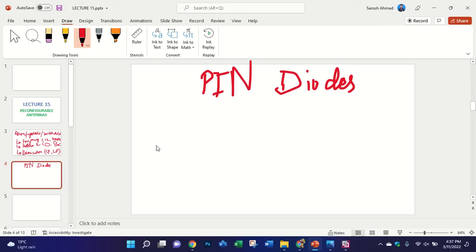In the case of proper biasing, we need to follow these steps. We have a PIN diode, like this diode. We will study the circuit diagram of this diode, because in CST or in HFSS you will not find the PIN diode directly. You need to assign some proper values, like a resistor, capacitor, inductor.